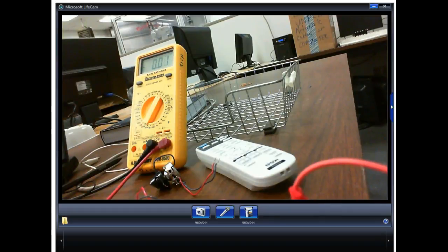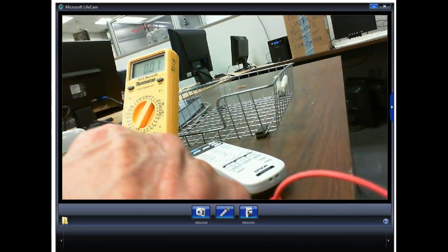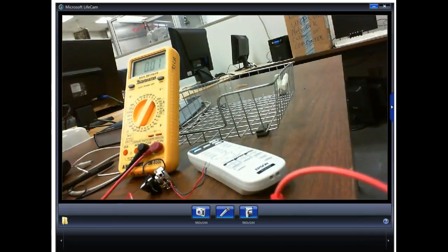My voltage collector to emitter. So here's my emitter. Here's my collector. Measuring 2.6 volts. Still not quite saturated, but it's close, right? So when we do predictions, let's don't try to come up with the actual value. What we need to do is determine if it's going to go what? Up or down.